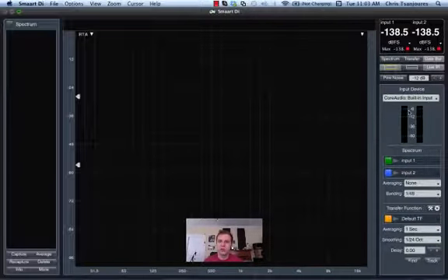The way that we are getting measurements in DI is that there are two spectrum engines which are paired to one transfer function engine. When you launch, the default configuration is input 1 and 2 on the spectrum, which are tied to measurement and reference of the transfer function. So input 1 is a measurement and input 2 is a reference signal.